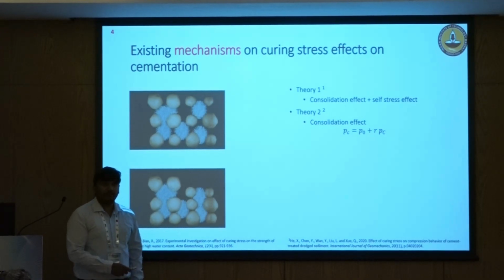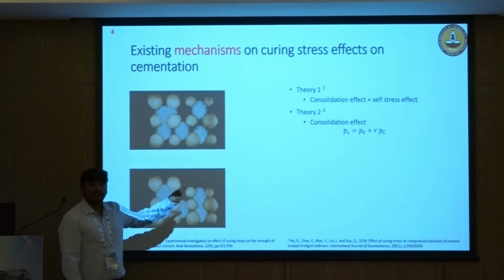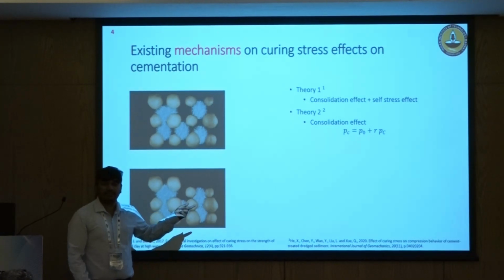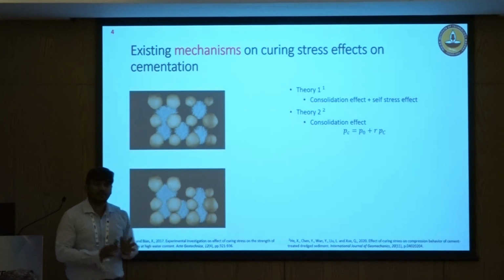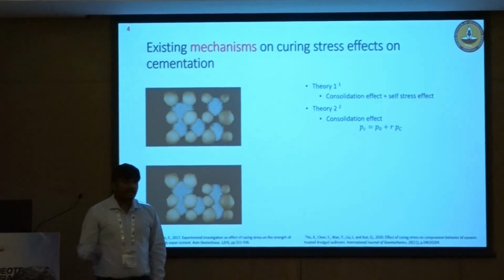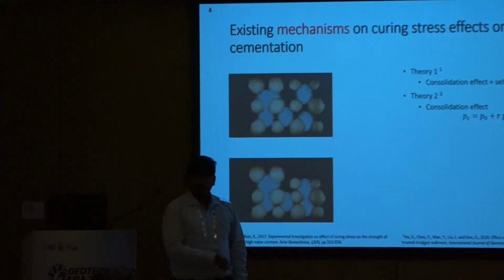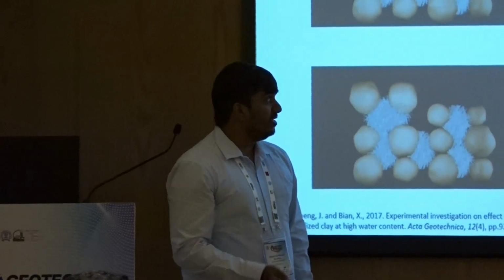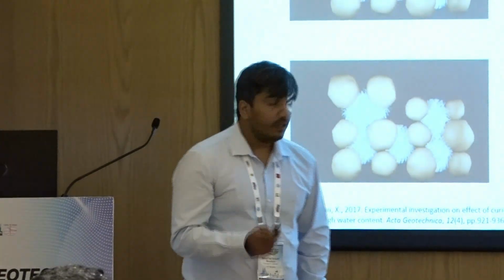First, the problem with these two theories is that they are postulates. They are not validated properly with experimental results. They are just postulated based on unconfined compressive strength tests. So we are going to perform a series of mechanical tests, such as unconfined compressive tests, tensile strength tests, and compressibility tests, to check whether these theories are actually working or not. Here, under the curing stress, R is always greater than 1.